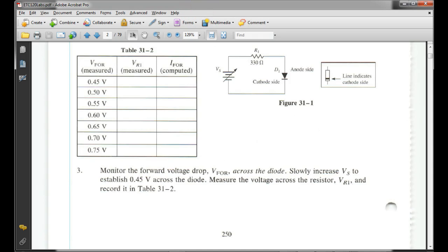What I would do is put my meter common right there. Then I'd take my red lead and put it right there. Now I'm measuring VR, right? Then I just move my red lead right there, and now I'm measuring VL. Your VF measurements are going to be negative, but they're not really negative. It's just because of the way we put our common on our meter.